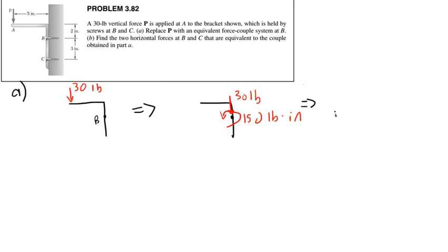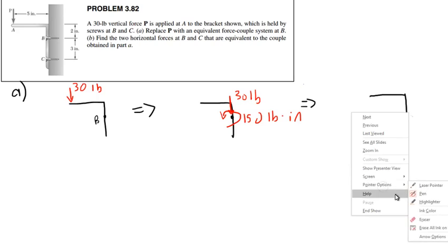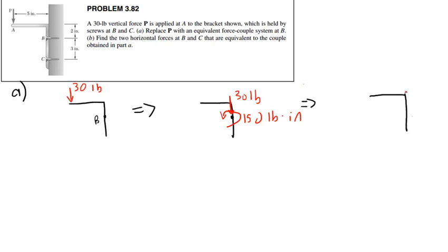Now, what makes this a couple rather than just a moment? Well, let's look at this. What could I do with this? I could say this is also equivalent. It doesn't matter where I apply this moment. I could say that it's also equivalent to this. This moment is not just a moment, it's a free moment.